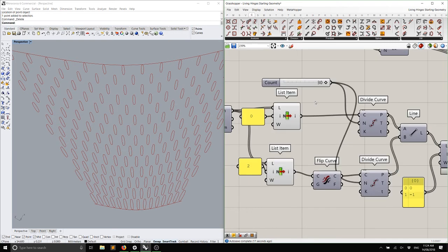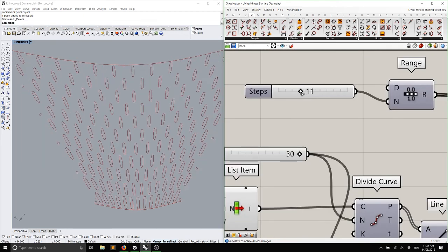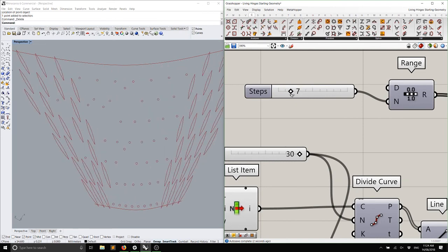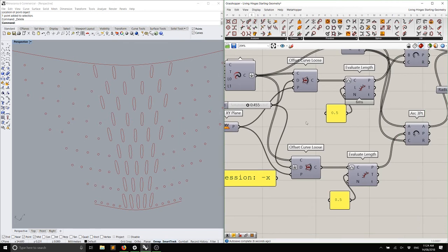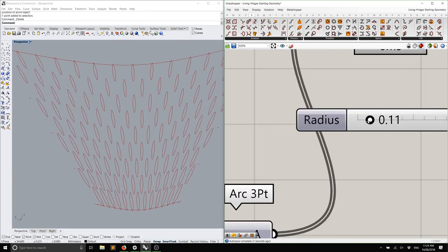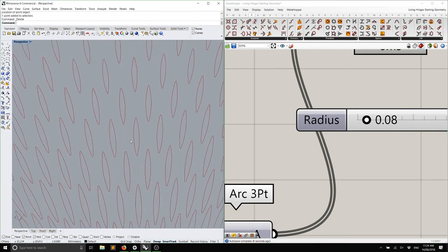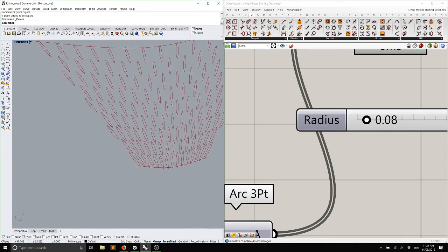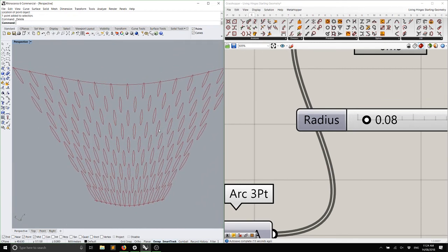And at this point you might start playing with having a bit longer lozenges, and the fillet in this case is the thing that's breaking us. You just want your fillet to be rather small, otherwise it's going to screw up your shape. But that gives you a nice little pattern that you can create across your living hinge.